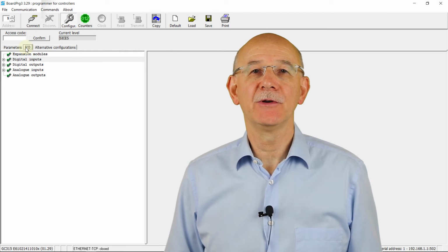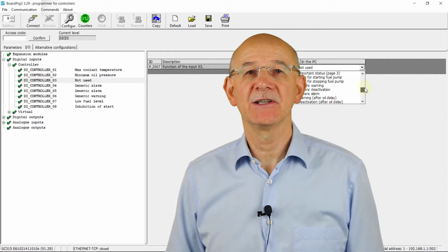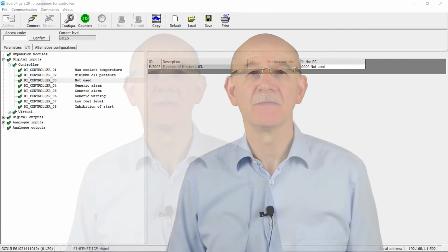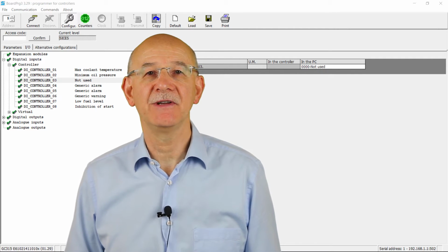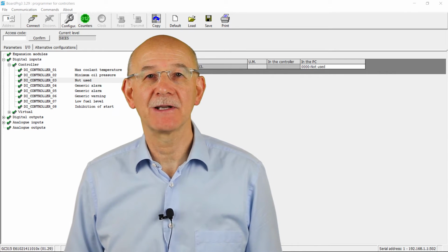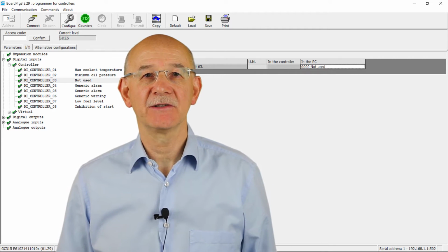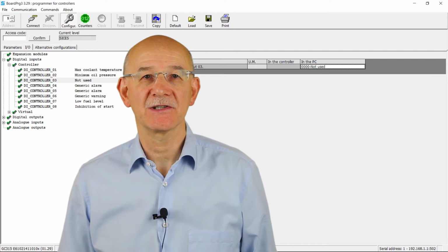More easily, the configuration can be made by the PC software board part3, accessing the tab I/O and selecting digital input and then controller. Here you can find the 8 inputs plus the analog inputs configured as digital ones, if any. Selecting an input, it is possible to change the related parameters. If the function selector parameter is set to 0 not used, no other parameters are shown. Otherwise, a list of 3 parameters will be accessible.